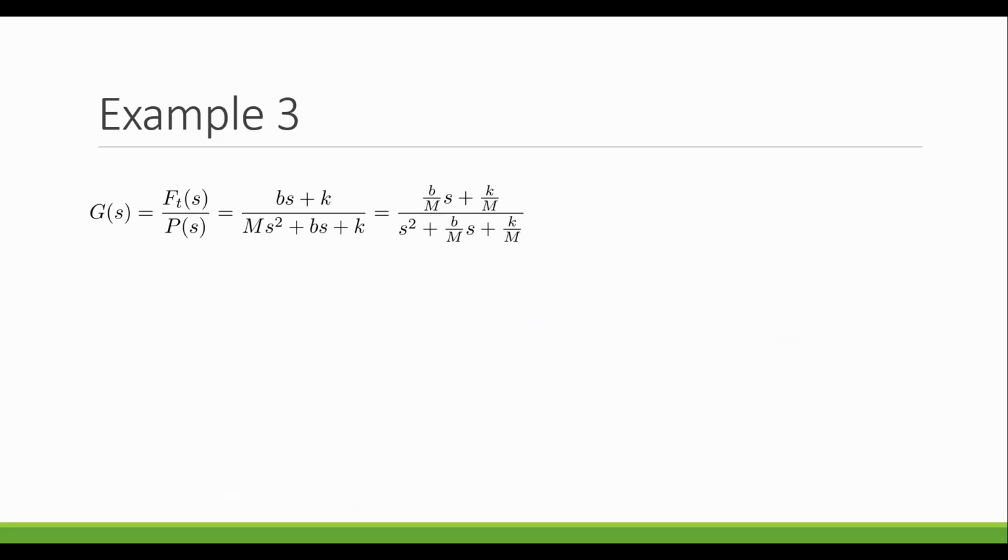Okay, so what do we do with this transfer function? M was given to us in the problem. That was the mass of the machine. But what we don't have is the K and the B. We are supposed to be designing that for this vibration isolator. So I can rewrite the denominator now that we are in the standard form with a coefficient of 1 in front of the s squared.